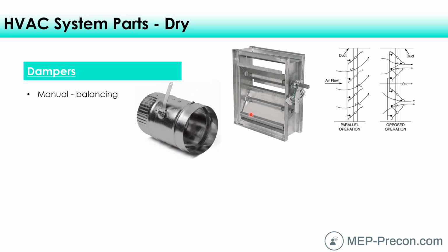And then with this type of damper too, it's important to understand some of the terminology. There are parallel dampers, and then there are opposed blade dampers. So here's a picture of an opposed blade damper where when you turn this, the linkage of the dampers, they will turn opposite. So within a parallel blade damper, they all turn in the same direction. When you turn the shaft, they all open and close in the same direction. With an opposed blade damper, each one moves opposite to each other.